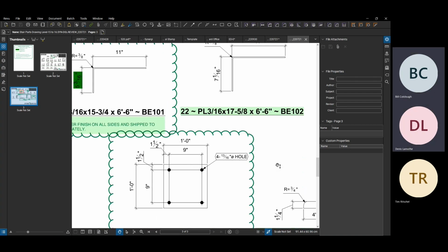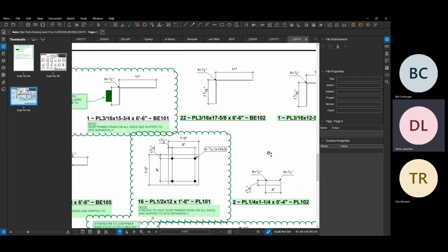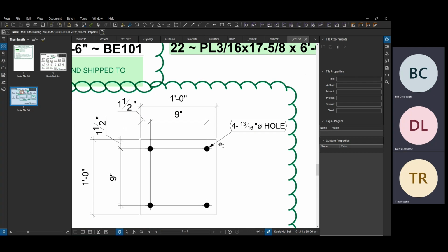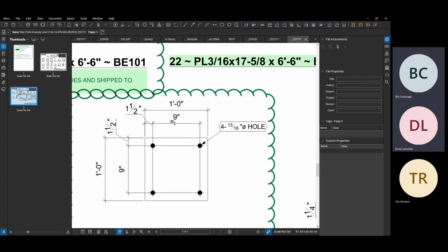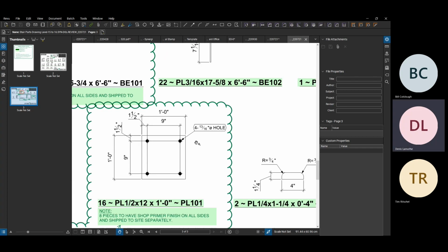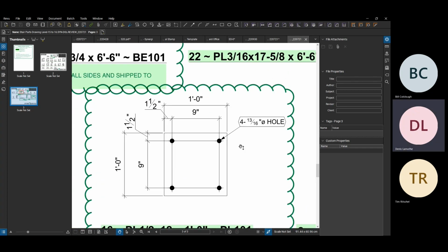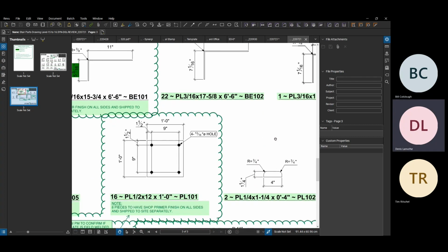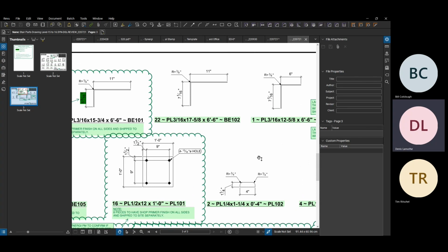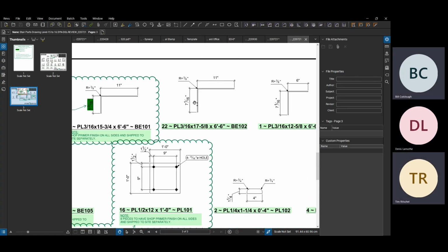So I don't do that frequently. More often than not, if there's a dimension between holes and they're equal, I may just dimension from the first hole to the last hole, say there are going to be 6 holes equally spaced at that, and call it a day. Or we'll use ordinate dimensions. That could be another way of solving that problem, but it's not something we typically need, to be a little bit more precise with our dimensioning.